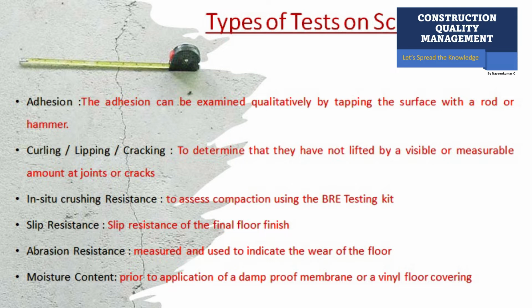Then next is curling, lipping or cracking. As the name itself says, we have to check the screed for any kind of lifting at the edges, which may be visible or measurable, and any cracks due to shrinkage, overloading, damage or a sudden impact on the surface, or any kind of lipping.